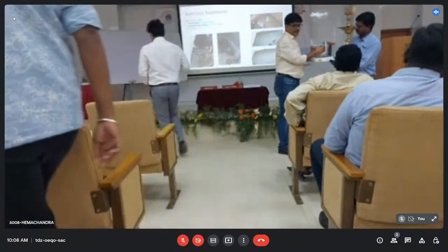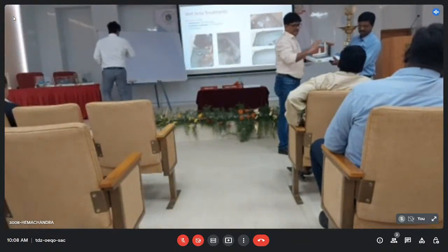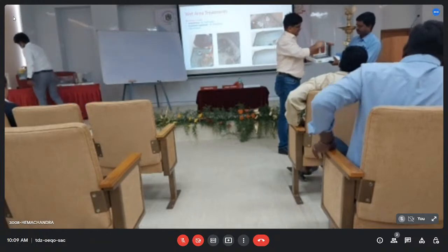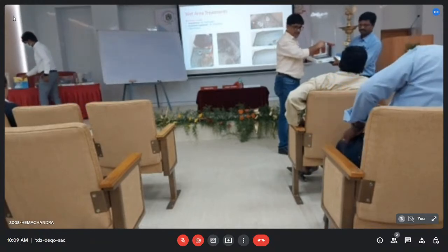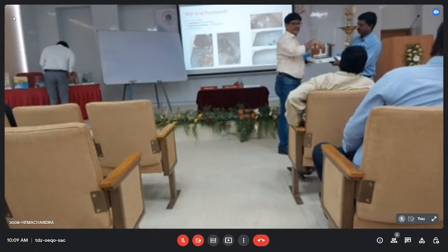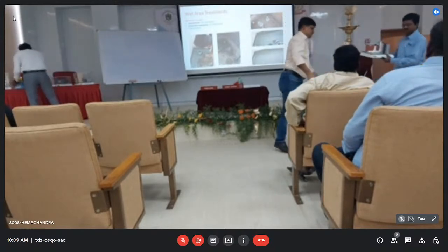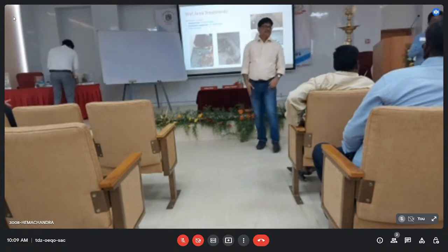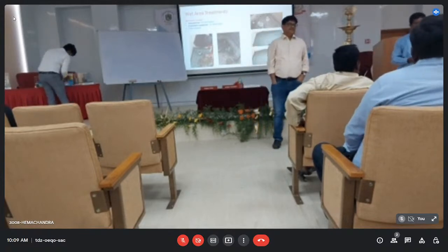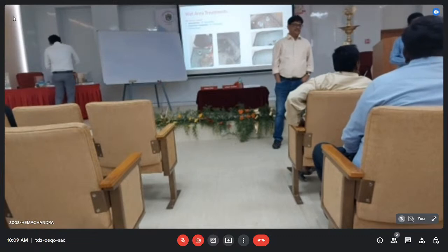Okay, so this will be done. He will talk about that. It's a bituminous tape. And then these sides have to be grouted. So that is the way the bore packing is done. Okay, so you will explain. My question is whether we can put this double-sided tape directly, or we have to rub the pipe and do it. No, you can put it directly.